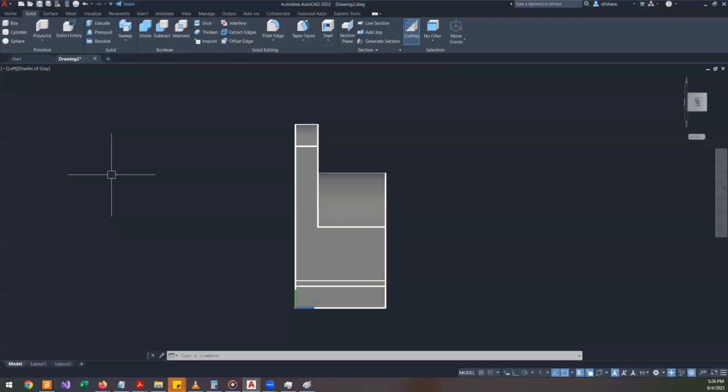Okay, so how do you change that? You right click and use the parallel. If you're using perspective, you will not get the correct output, basically. So don't use the perspective. You must be using the parallel. It is a must, not a should. So you right click on the view cube and select parallel. Okay.